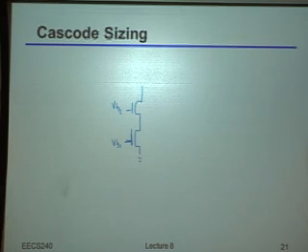What's the number one, most important thing about a current source? High output impedance. Yeah, high output impedance, right? So, at least at DC, for the transistor, what are you going to do to make it have high output impedance? Let's start with channel length. Yeah, make it long, right? That's indeed the most common thing you'll do: pick a long channel length.